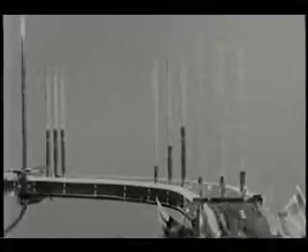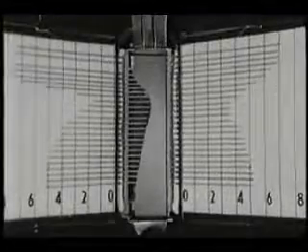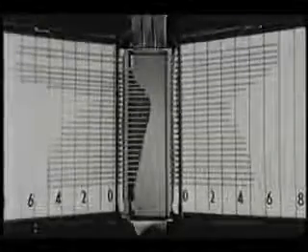Another example of streamline curvature is the throat of this half venturi. The throat pressure at the curved wall is considerably less than at the straight wall because of the streamline curvature. When we use venturis for flow measurement, the pressure we measure at the wall is therefore not the average pressure at the throat. That is one reason for calibrating venturi meters.